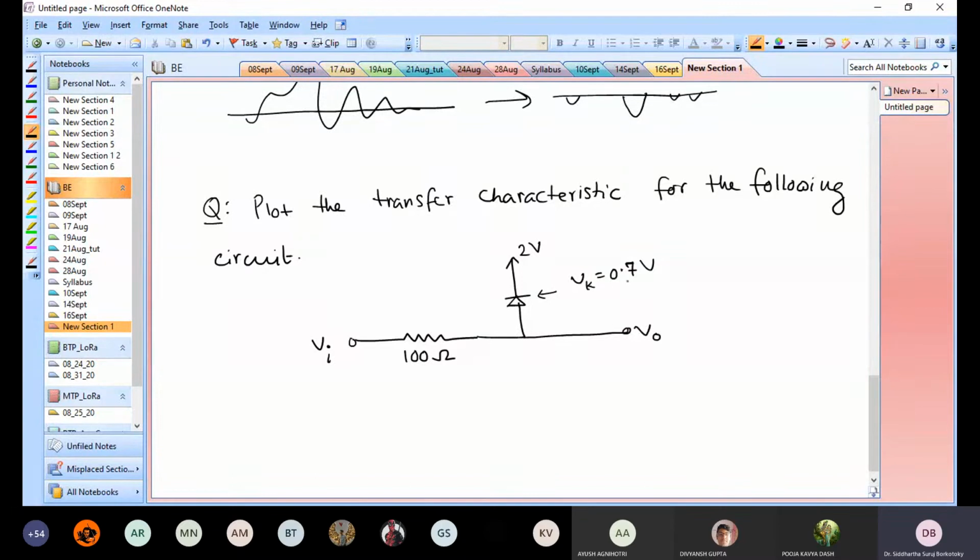Either way, you know that there is this threshold of 0.7 volts that needs to be crossed. We will be dealing with silicon diodes, so that term will always be 0.7 volts. If you're using a germanium diode, in the rare case, then you'll see 0.3 volts. But if you see 0.7 volts, you'll probably know that this is a diode with a barrier potential of 0.7 volts.